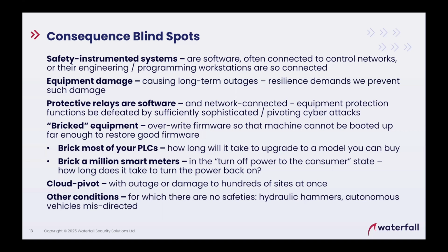And there are other conditions that you cannot build safety instrumented systems for. The one I'm familiar with is in pipelines: the concept of a hydraulic hammer. This is a high pressure condition moving through the pipeline at the speed of sound. A couple of these hydraulic hammers collide and the pipeline ruptures. You can say we have overpressure relief valves at locations where the hammer tends to happen naturally. But if you bring it about deliberately, we could, in principle, cause the pipeline to rupture anywhere along the pipeline. So there is no safety system for that.